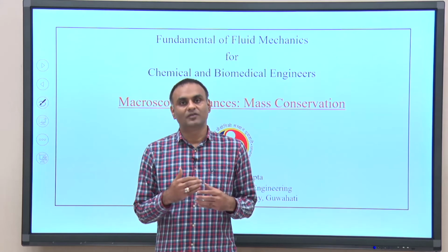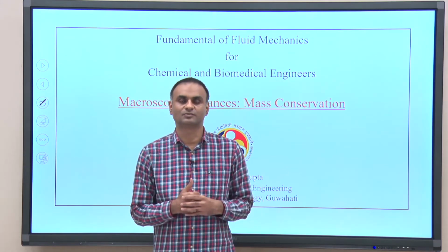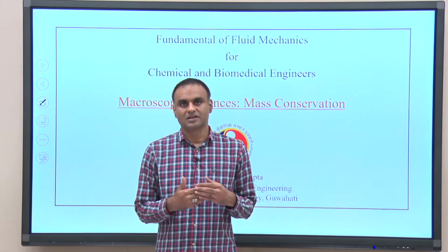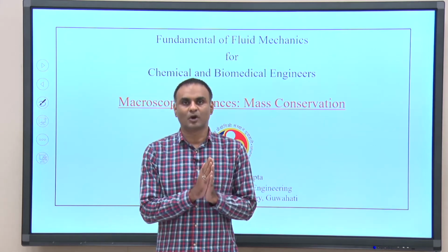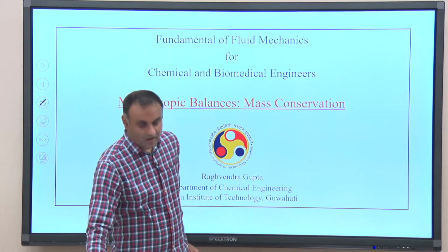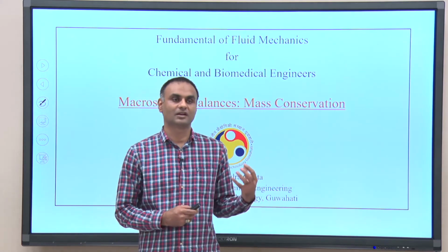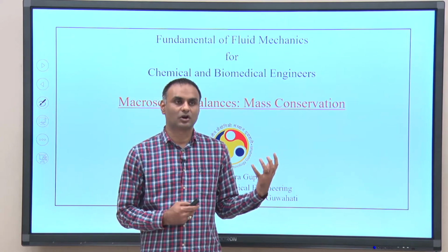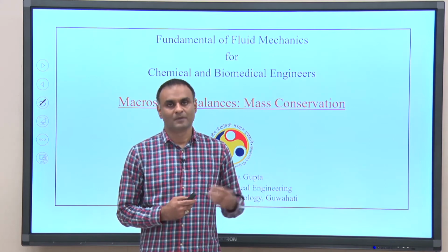So, what we are doing in this week or in this module is we learnt first that for a general variable n or an extensive property n and the corresponding intensive property eta, we derived the Reynolds transport theorem, that is how we can convert a derivative in the system form, because all the equations have a dn by dt kind of term.